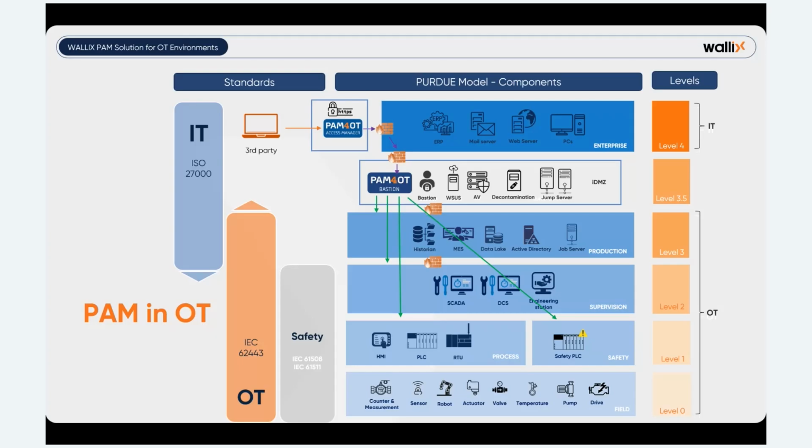If you are inside the refinery, or if you are inside the substation, we also give you an option to connect to the Bastion directly on a GUI, which eventually connects to your engineering workstation. Now, why is this important? Why are we segmenting it like this? Because this segmentation is enforced by IEC 62443 compliance. This is a global compliance which ensures that all OT factories and companies follow a standard of safety and security.